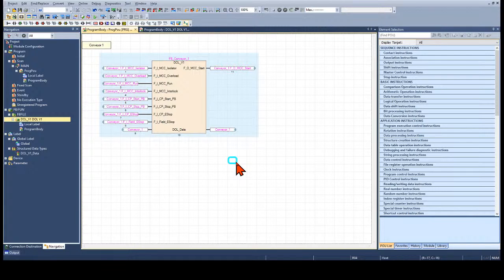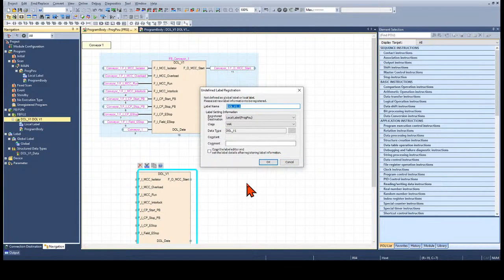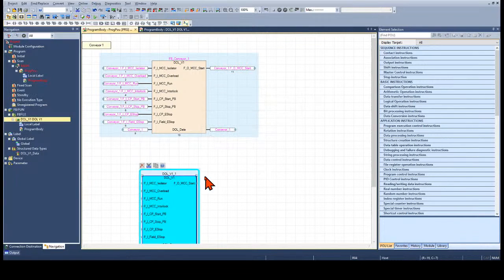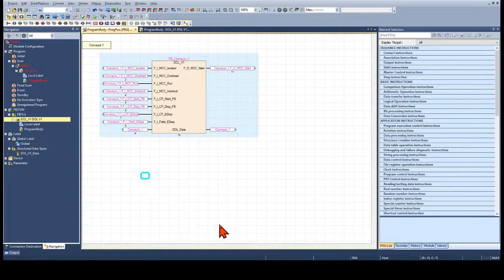So now we have created the function block, and we've created the document to support it. I can drag this function block into our program 500 times if I have 500 conveyor belts. I don't have to write the program over and over and over. So that's the advantage of using function blocks, and we're keeping to a standard that we've defined previously.